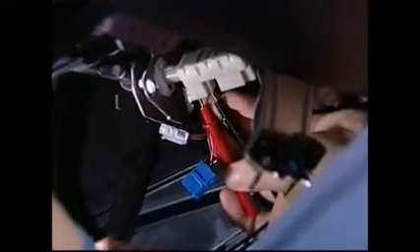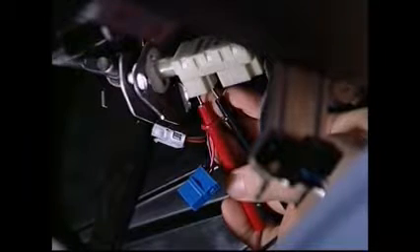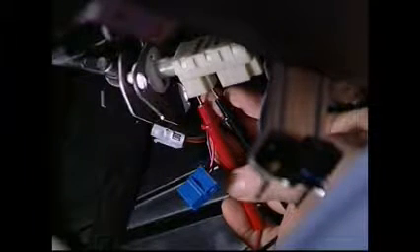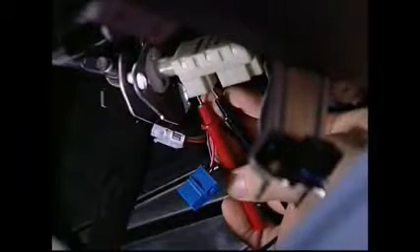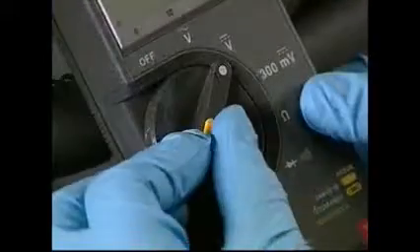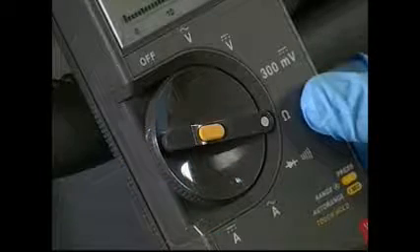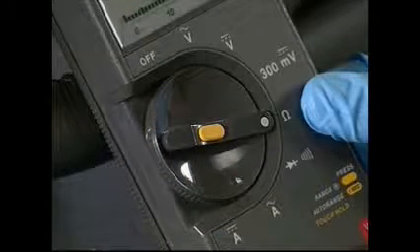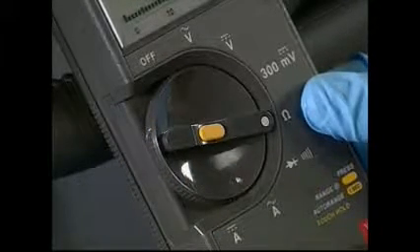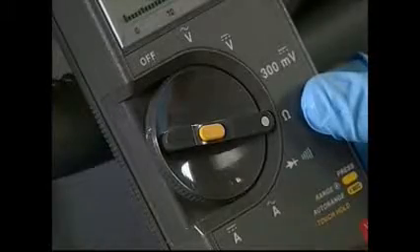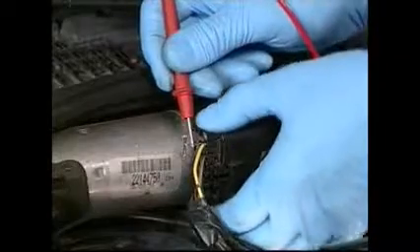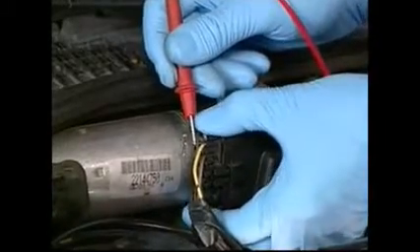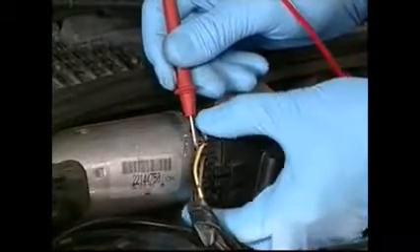We just saw how the beeper function of a digital multimeter can be handy in confirming continuity. This function is particularly helpful in testing connections for intermittent open conditions. To check a connector for an intermittent open, set up the meter as you did for the stop lamp switch test. Press the alert button to set the audible tone, then insert the probes on the opposite sides of the same connector terminals. There should be a continuous tone from the meter indicating continuity.